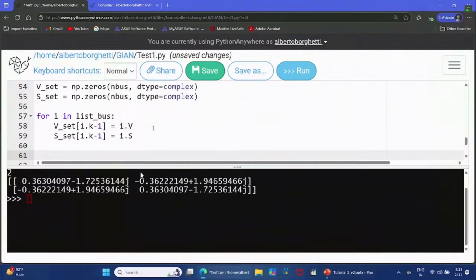In this problem, you see that you cannot classify the buses as the normal PQ, PV, slack, because in this bus, you fix the active power, the reactive power, and also the voltage. So we can say that this is the receiving bus in which we fix P, Q, and also V, and this makes the solution of the system very simple. And here in the sending bus, I don't fix anything.